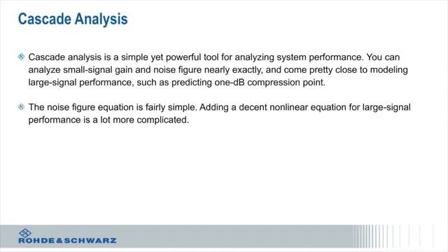Okay, so when you put all these things together, you have to do what we call a cascade. So really what the cascade is doing is trying to reduce everything, all as separate entities, like separate amplifiers and mixers, and then moving them all to look like one device. So what is the overall intermod product? What is the overall noise figure? What is the overall gain of my system? So we have, again, tools for doing that, but you need to be aware of what's going on.